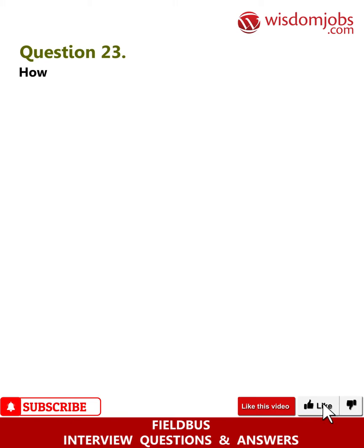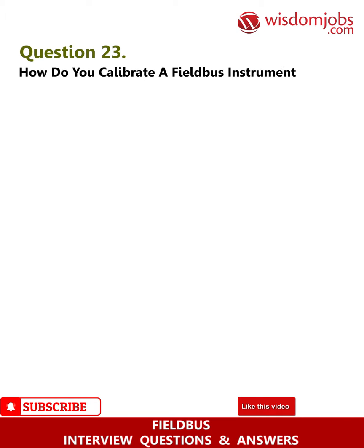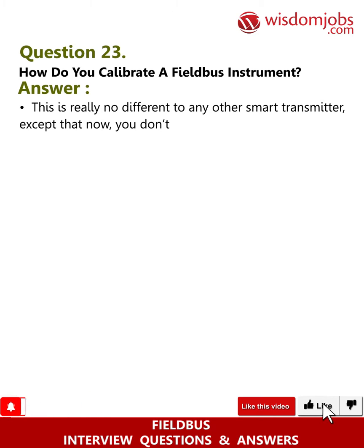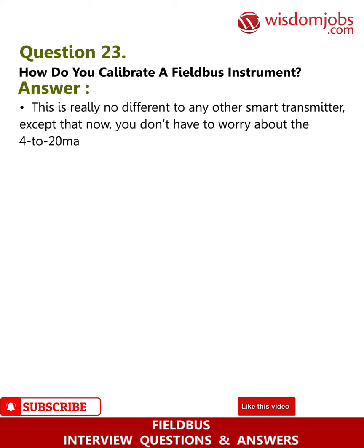Question 23. How do you calibrate a Fieldbus instrument? Answer. This is really no different to any other smart transmitter, except that now you don't have to worry about the 4 to 20 mA analog signal.